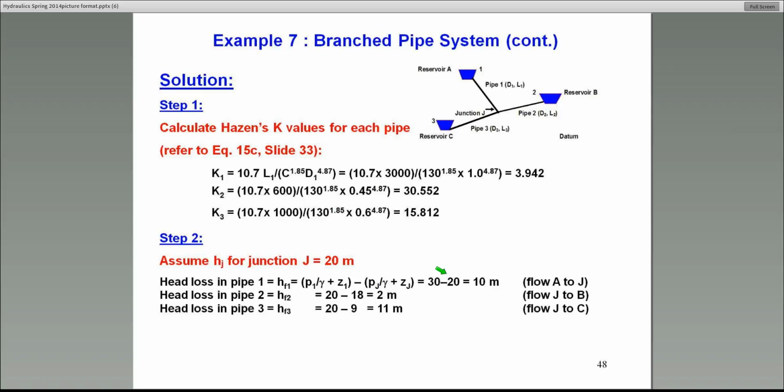Is critical flow part of Manning's on the exam? Well, it could be, because critical depth is a very important depth in many open channel flows. In most hydraulics courses that we teach, I do cover some open channel hydraulics as part of that first course, so I would expect similar questions on the exam.